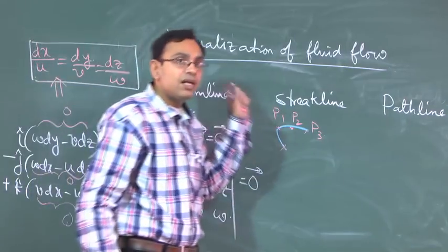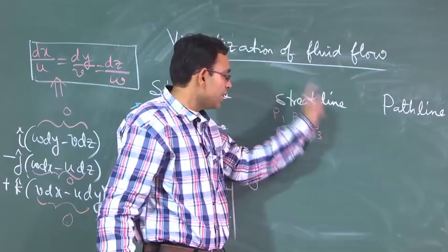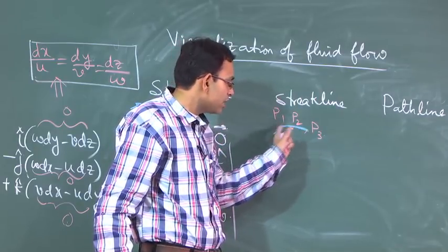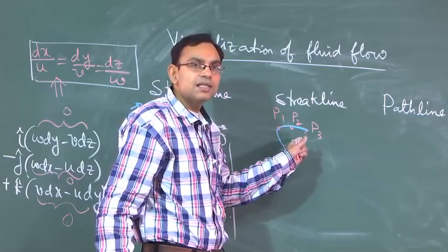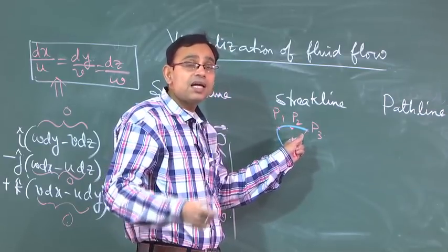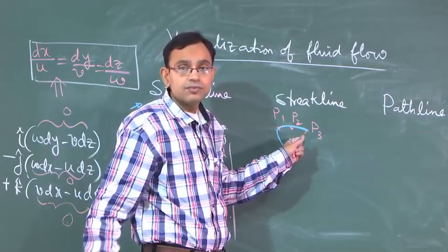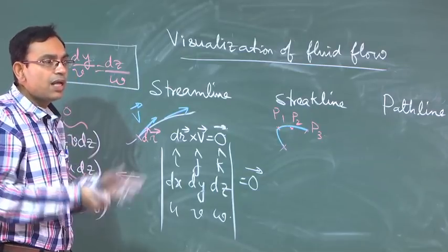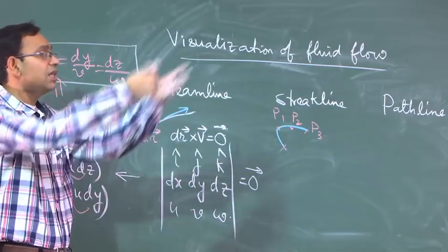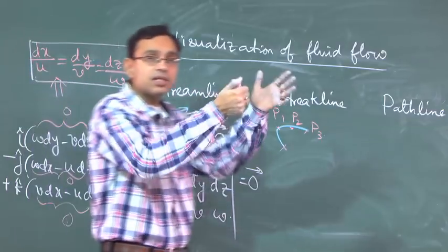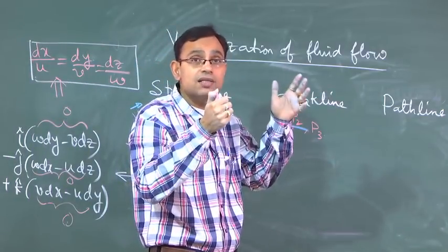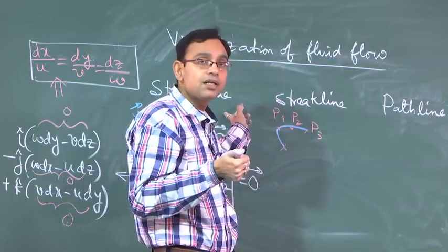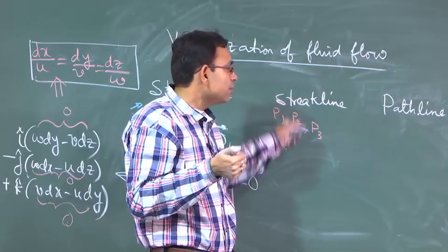We have to understand very carefully that the streak line, which is what we are conceptually considering as a definition, is physically the colored line that we see in the experiment after dye injection. Loosely, many people after doing this experiment will say, see the streamlines, but conceptually those are not streamlines, those are streak lines. But under a specific condition the streak line and streamline will be identical, and we will come to that in a moment.